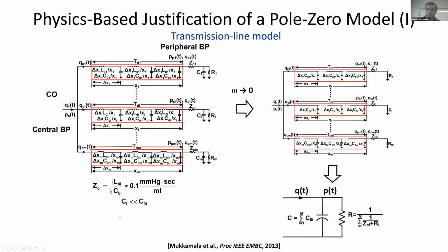And further, since the small artery compliance is much less than the large artery compliance, the load capacitors open before the line capacitors. So at low frequencies, each line becomes a parallel connection of capacitors while each load becomes a series connection of two resistors. All of these elements may be lumped together to arrive at the RC circuit model shown here. So this transmission line model reduces to this model at low frequencies, which is consistent with our overall idea.